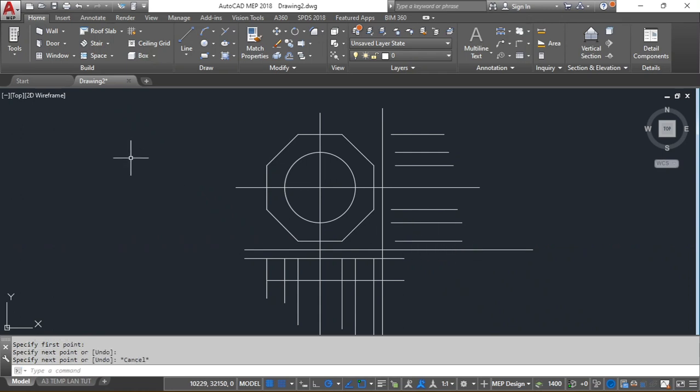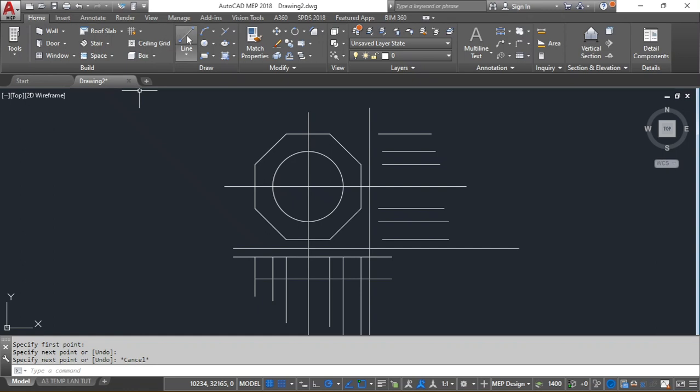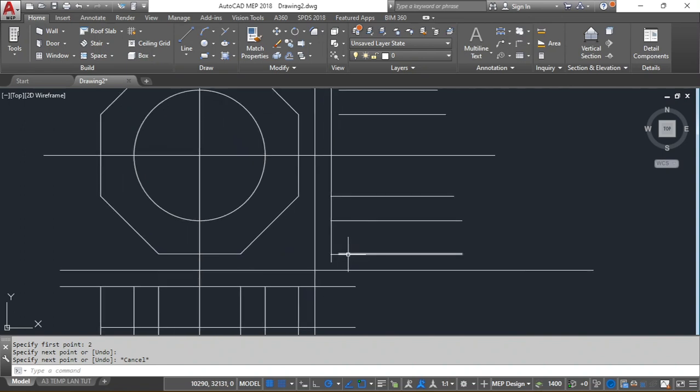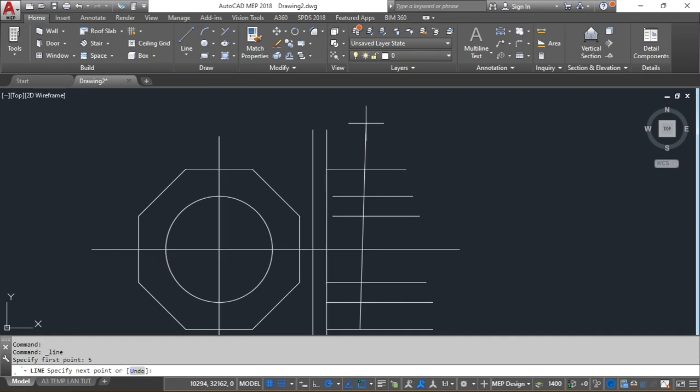Okay, escape. Then one last point there. Okay, now we need to draw a vertical line. It should be 2 millimeters from that point. So, and it should stop around there. Okay, so hit escape. Make sure this one crosses or intersects with that line. Now we need another vertical line from there to somewhere, it should be 5 upwards.